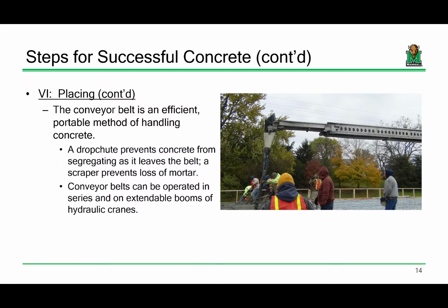There is no bridge for the trucks to cross, right? So the concrete trucks would show up. The batch would deposit onto this conveyor belt system, and then essentially the concrete would be conveyed along this extended boom crane, and then it would be placed right here. It was really simple, but it was really slick how they were able to deposit and place a lot of concrete in a very short time.